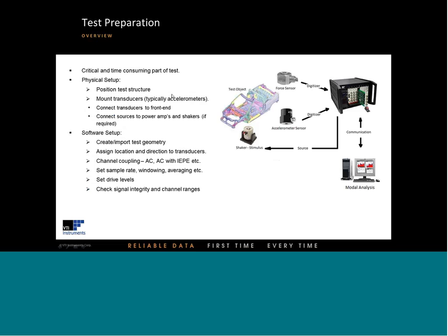So, test preparation. We have the test geometry. First of all, we start with the physical setup: position the test structure, mount transducers, which would typically be accelerometers, connect transducers to the front end, connect sources to power amps and shakers if required.